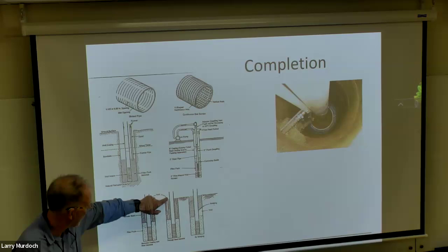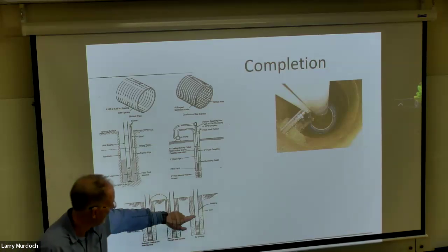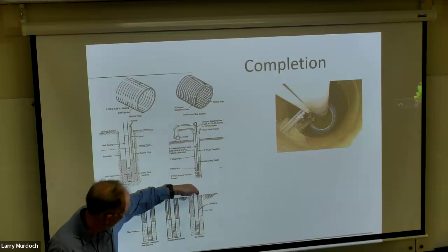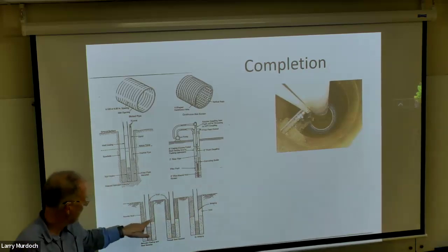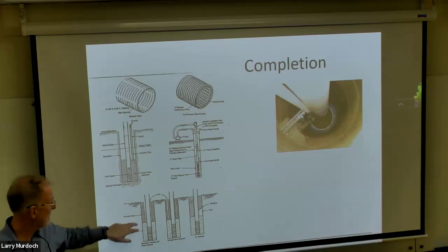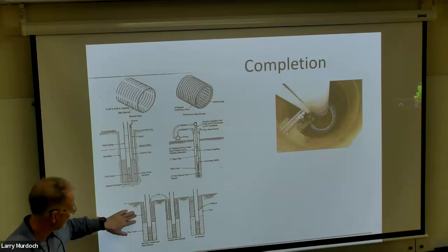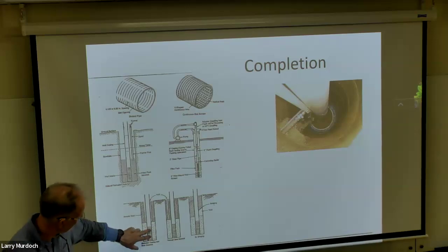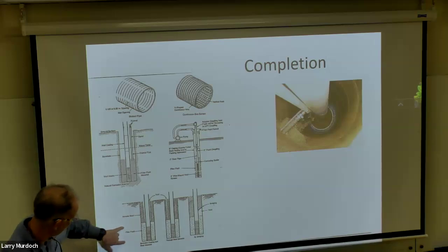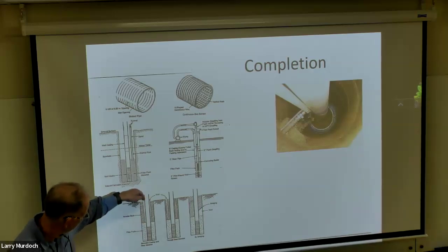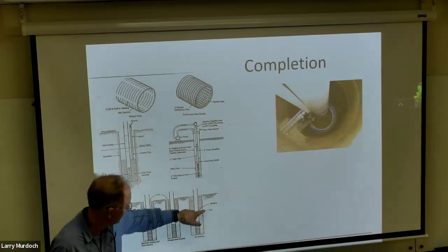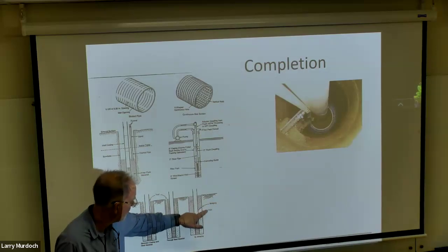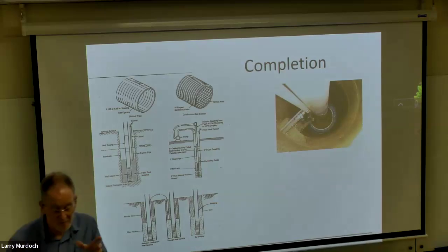This is a crack in the annular seal, and this is a place where, when you put the material in from the top, it bridges and doesn't reach the bottom. So all of these are problems because they compromise the seal. And it means that the water that is getting pumped out here isn't necessarily coming from right here. In this case, there could be contaminants coming from the ground surface. Here with bridging, there could be contaminants coming up from a shallower depth.